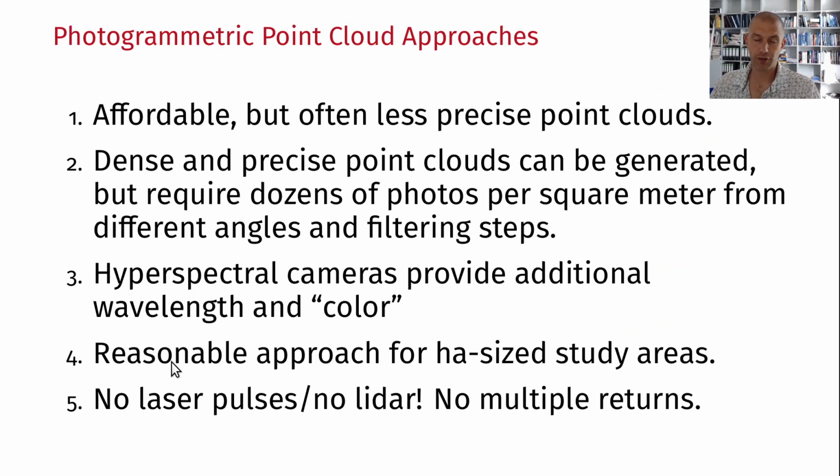Drone-based approaches or structure from motion-based approaches are usually reasonable for hectare-size study areas. In other words, when you have a 1 by 1 kilometer area, or maybe even a little more, drone-based surveys are reasonable. If you end up having a 10 by 10 kilometer area, then you likely would like to use different methods, because the amount of data that you have to collect and the difficulties in the logistics are fairly high.